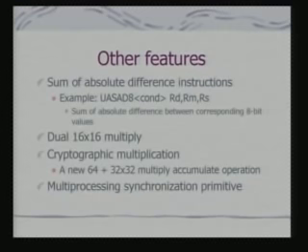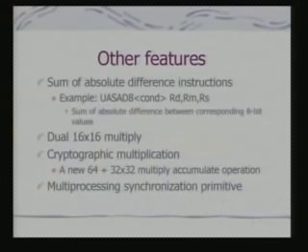And you can consider that if I am trying to compute the difference between two small image areas consisting of pixels, okay, what I shall do? I shall subtract the values of the pixels and add them up, and that would give me the difference over a region. So in this case I can use one instruction to compute difference over a set of 4 pixels in the image if you are using 8 bits per pixel.